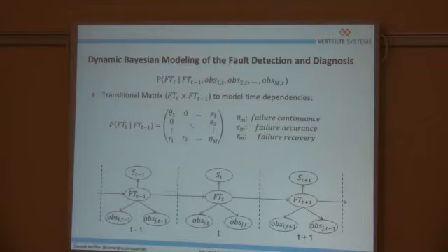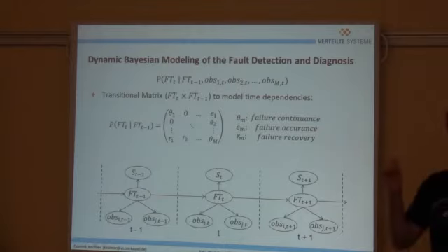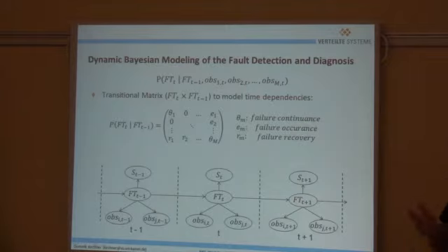See what's the current supply voltage of one board. If it drops down to 5 volt and you assume 12, obviously you have a problem. So that's the hardware monitoring tool. You need to do exactly the same approach for your hardware component. We've done that with voltages, with temperature, even with some sound. The idea was if you shoot with your robot, you should hear some sound. If you don't detect that sound, your shooting device obviously doesn't work well.